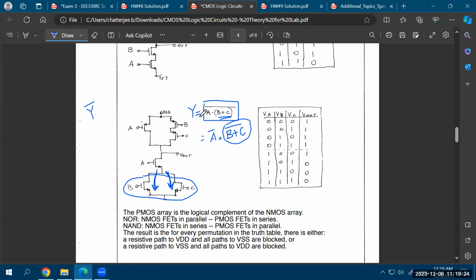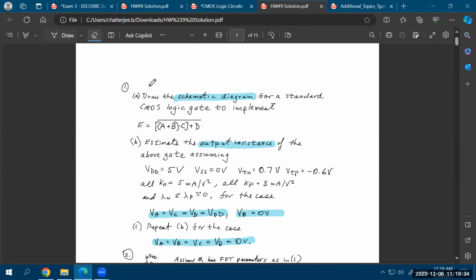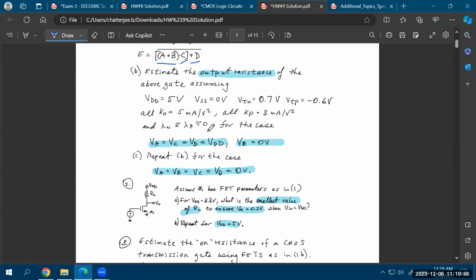But of course, there is the other solution that some of you talked about, that I can just represent this arbitrary function. For example, you had this arbitrary function over here, right? A or B ANDed with C or with D. You can represent it as a combination of NAND gates, NOR gates, AND gates, OR gates, all different kinds of gates, and draw the internal structure of the gates. But again, you'll probably use 30 transistors in that case, instead of the 8 or 10 transistors you'll need if you represent it efficiently.